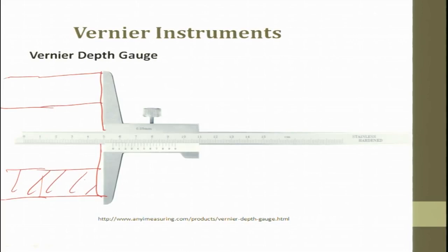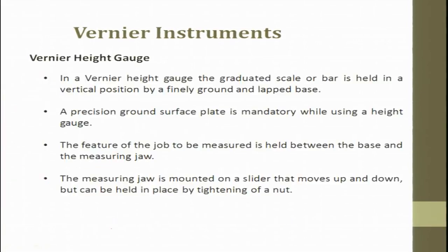So, this is a component, this is the depth, and again this is the main scale division and this is the vernier scale division. First slide, get the 0 value and then we see a matching value, multiply it with some factor which is given here. So, with this 0.05 division we multiply and then we try to get whatever is the answer.